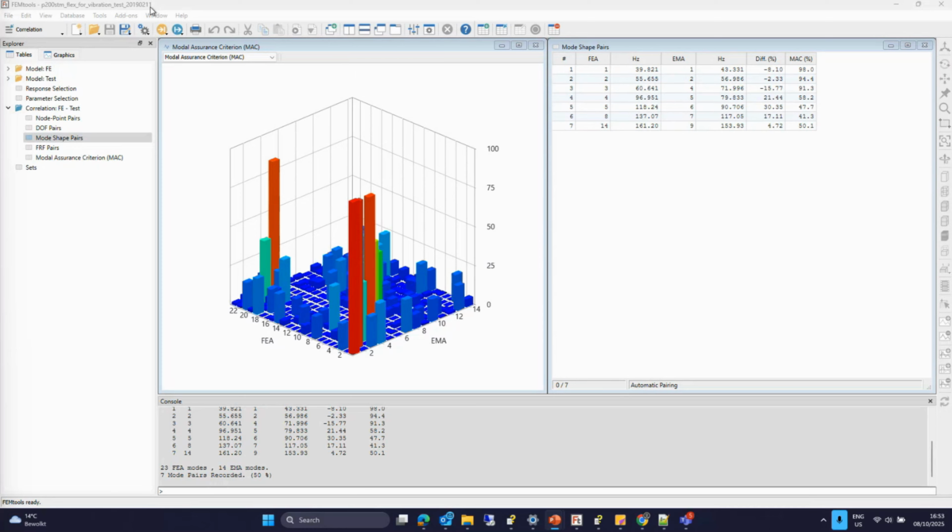And in the general case, there are actually 3 files that we need. One is with the mode shapes. In this version, it has the extension .51. This was the .4.51 file that Kelvin imported. And then we have one with the element stiffness matrices, .91, and one with the element mass matrices, .92. So these 3 files,